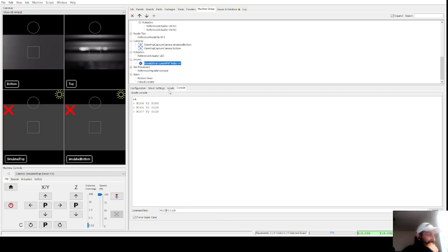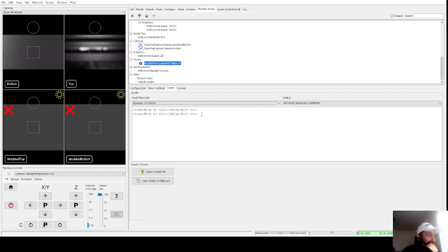So that is the VAC1. Actually, that was VAC2. I just know that was VAC2. So this is 0, and this is 1. And this is 0, and this is 1. So I can say apply here, and then I'll go right to VAC2, and I know that's the one I should have pasted there. So port 2, port 3 is pump 2 and vacuum valve 2. So that's the move to command.